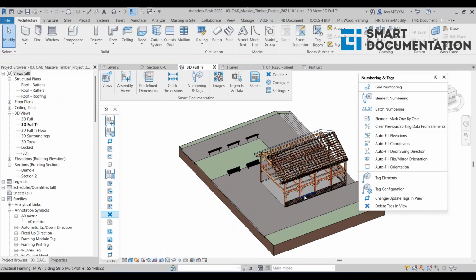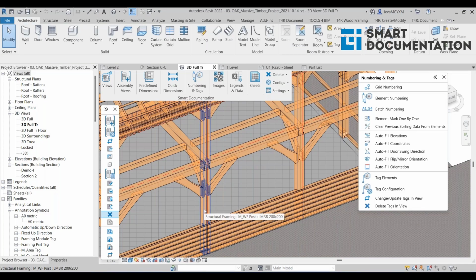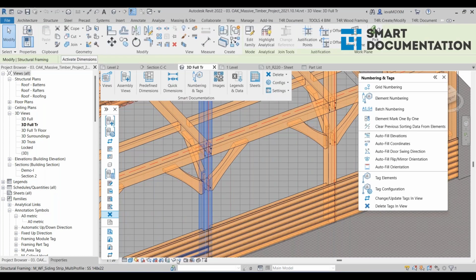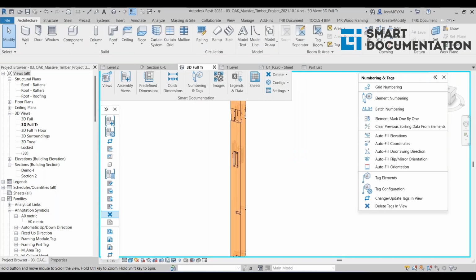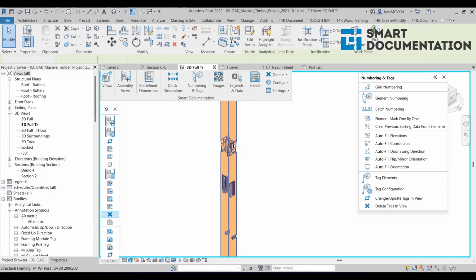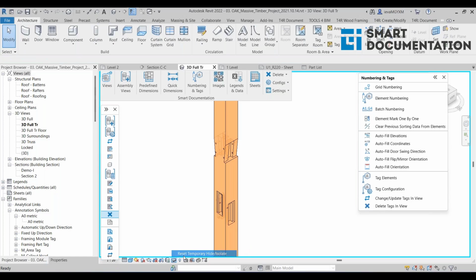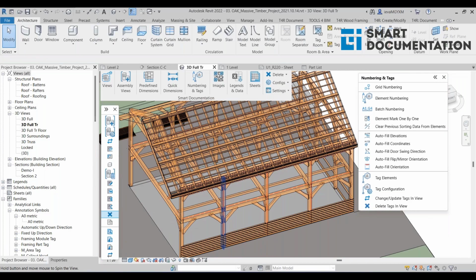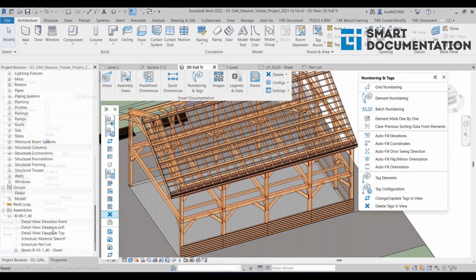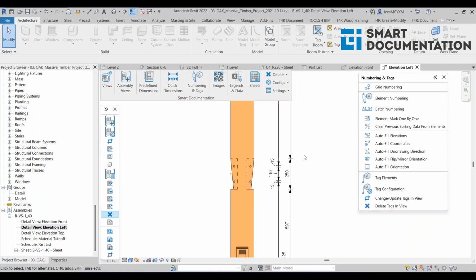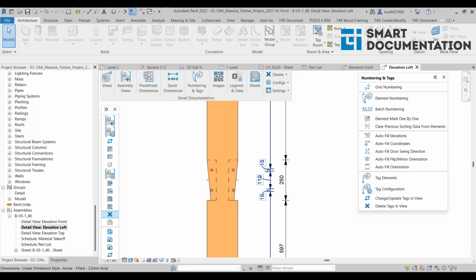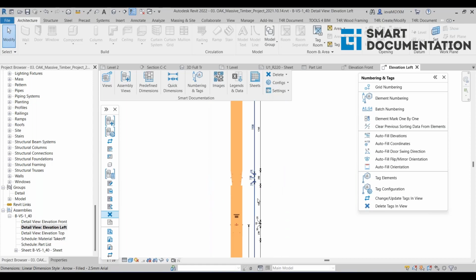I have this project with complex beams with connections, braces, and they have a lot of complex cuts in them. And again, of course, we need to document that. We need to show that in our shop drawings. And with Smart Assemblies, again, we can just create a configuration. The shop drawings will be generated. So let's see here. I have this drawing where you can see even the dimensions were moved automatically so that they wouldn't intersect with each other.